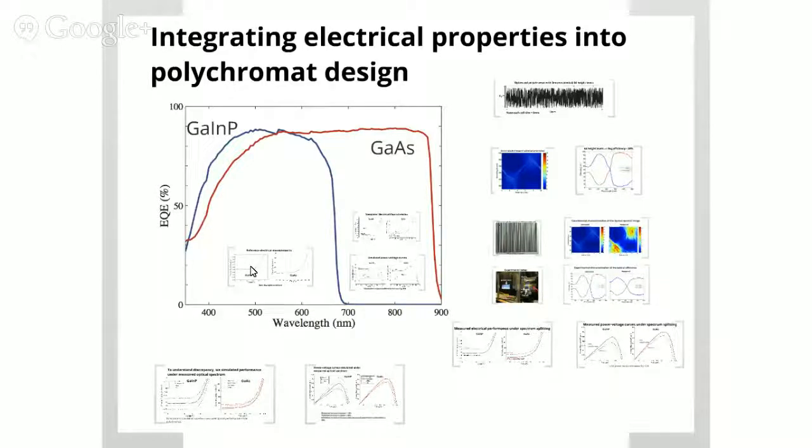That's the idea here. So in this example that I'm going to show you, we use gallium indium phosphide, which has this blue external quantum efficiency curve, wavelength versus EQE, which EQE is essentially the probability that the photon coming in will get absorbed and form a current. Okay, so it's high probability for the visible photons. Okay? And gallium arsenide, which has something which looks like this. Okay, so the idea is you want to capture this part of the spectrum for gallium indium phosphide at high voltage, and this part of the spectrum in gallium arsenide at slightly lower voltage.